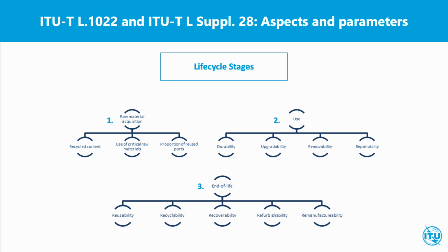Remanufacturability. Remanufacturing is usually performed on good or part level. Remanufacturing activities are likely to contain inspection, test, disassembly, rework, cleaning, reassembly, and reinspection. Remanufacturing primarily addresses goods, parts that do not meet the quality specifications. A remanufactured good should have the same or better quality as a newly manufactured good.